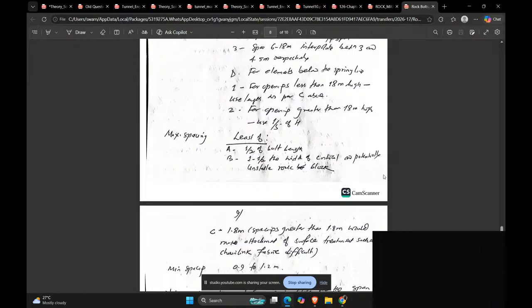The borehole and the geophones were positioned so that the first geophone is 20 meter below the borehole top, with the source of the impact 40 meter away from the borehole, and the second is 40 meter below the borehole top. Calculate the seismic wave velocity from the downhole tests using the vertical distance and travel time.